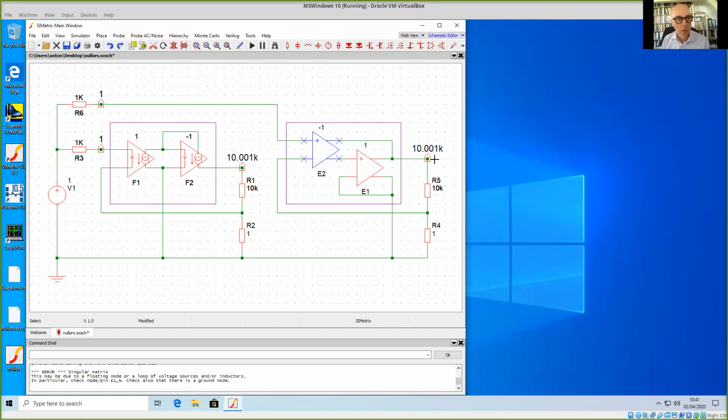That is how you define the sign of your controller if it is not a nuller. But if you change it, it doesn't do anything. Because you see here, with a nuller in, you can change the sign here, but it's not important at all. So the only thing that matters is the sign of the loop gain, and that is all.